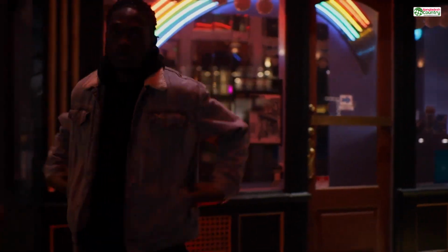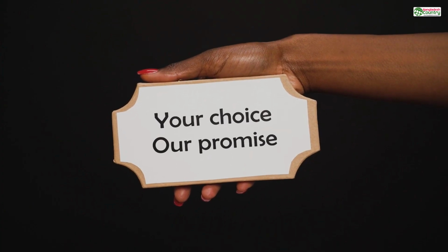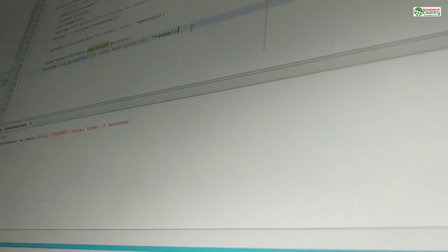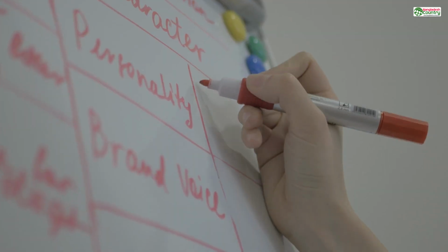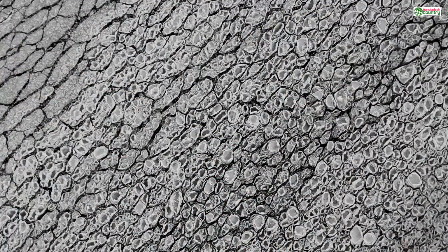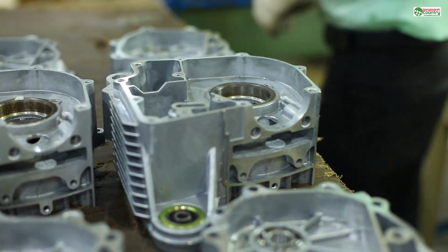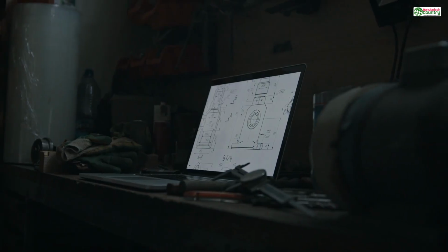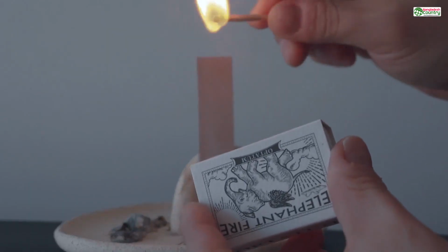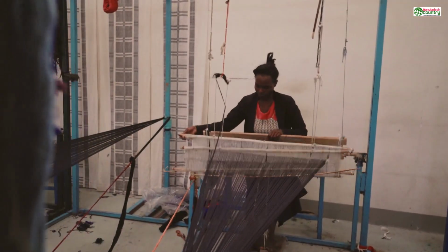So before you upload, ask yourself one critical question. What is the purpose of this part? Is it a display piece? Go for high detail. Is it a functional part that just needs to work? Go for draft and save some money. Is it something in between? Stick with standard. By making a conscious choice based on your part's purpose, you're taking control of the process. You're not just clicking a button. You're making an engineering and design decision that optimizes for what truly matters to you.